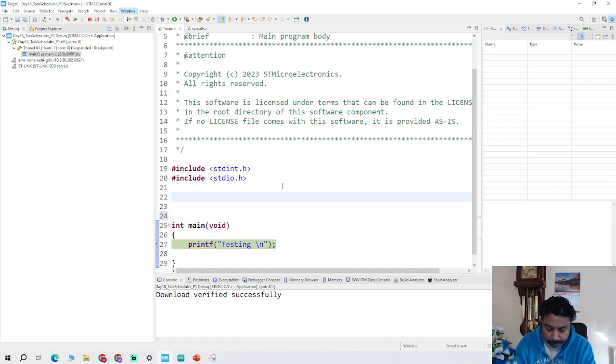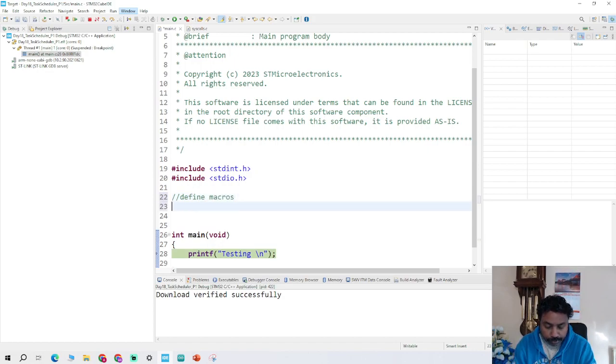So I'll define some macros first. Start off with #define the size. The 128 kilobyte size we are calculating, taking 1 kilobyte from that for the stack. So size of the task stack, with 1 kilobyte.